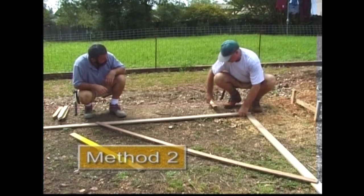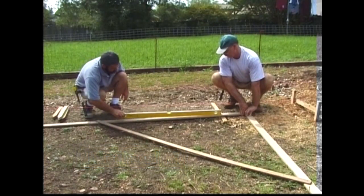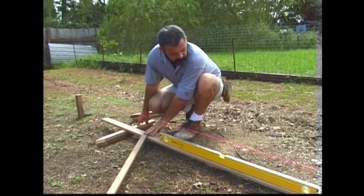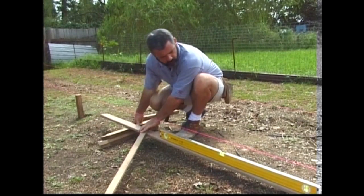An alternative method to establish a right-angled corner is to use a builder's square. This consists of 2 timber arms fixed at the corner and braced to form a right angle. When placing the square at a corner peg, at least one of the arms must be level to produce accurate results.